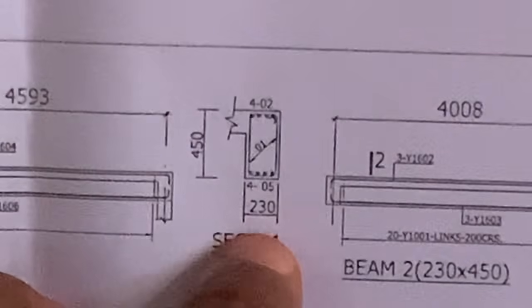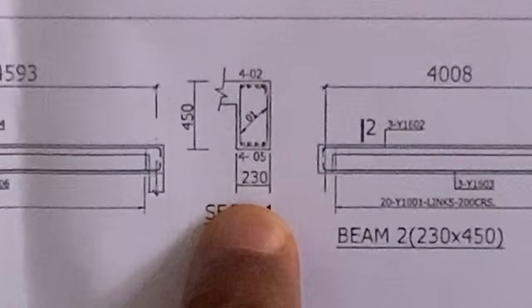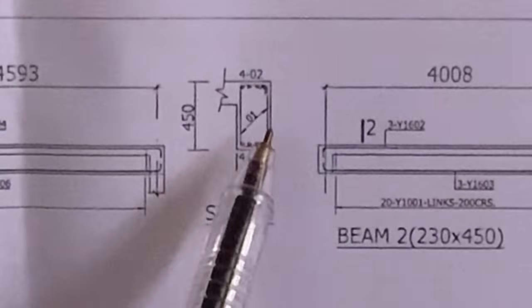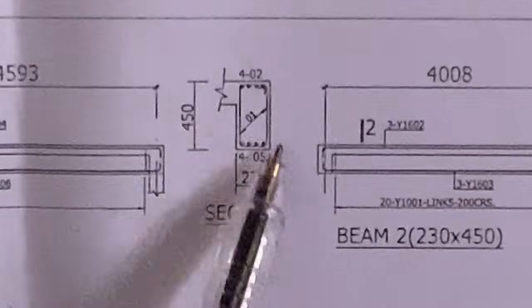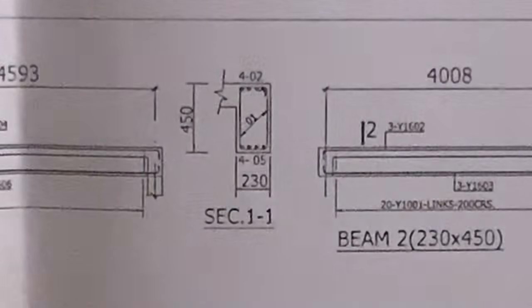So now, just know that your suspended floor is connected to your beams, right? So if your suspended floor is connected to your beams, how do we now calculate for our beams and our suspended floor separately? Because they are two different work items. You don't measure them together. The drawing says that when you are constructing, the beams and the suspended floor are constructed together. However, when you are measuring, you have to separate them.